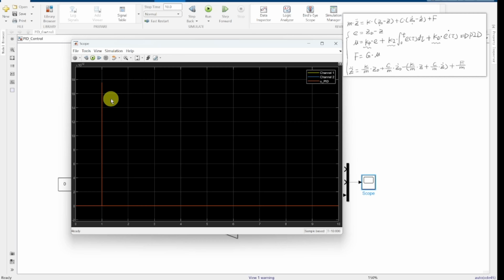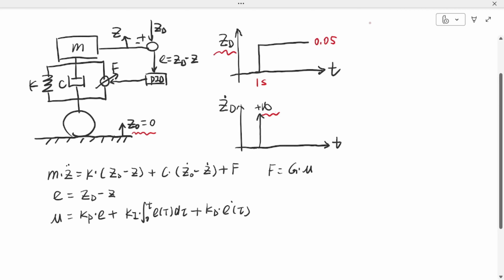Let's take a look back at the standard PID control equations. Let's return to the motion equation. The KD term, this term here, differentiates the error E, which mathematically requires taking the derivative of the reference value itself. Since our reference is a sharp step input, its derivative instantly spikes to infinity. Knowing this, it's no surprise that such an astronomical input current is generated.